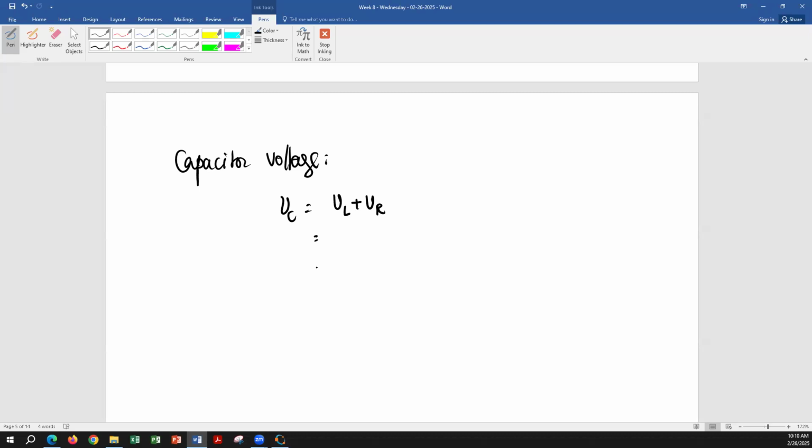Yeah, it did change. Capacitor voltage cannot change instantaneously. Capacitor current went from 0 to IL, because it was open, and the voltage it had across the open capacitor, 12 volts, is not changing. But at 0 positive, the capacitor current becomes 2 amperes, from 0 amperes to 2 amperes. So it did change instantaneously.